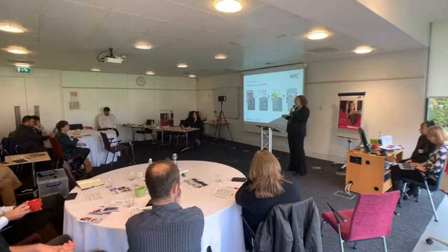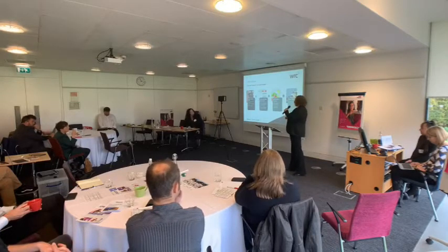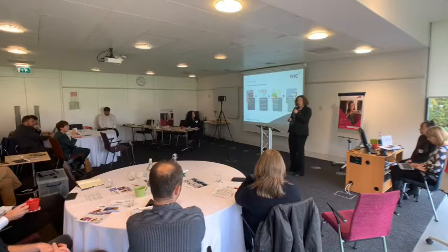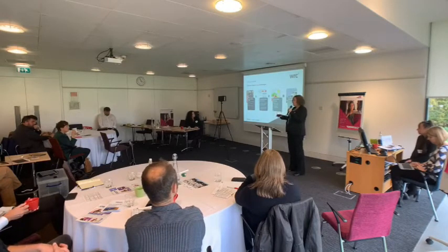Once you've got all that metering in place and you've got good high quality data coming from them, then you can actually start to do upstream losses assessments, which in turn means you can define interventions, whether that's going out finding leaks, reducing uncertainty, or working with customers to prevent surge in a network, whatever it might be. You can actually say this is the right intervention to do in the area.